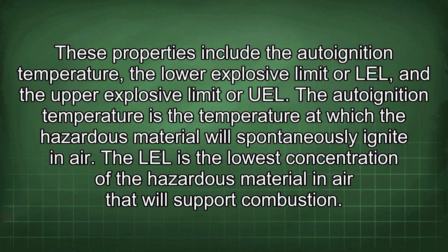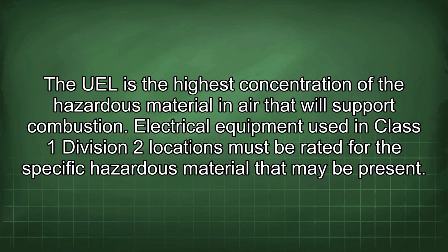The auto-ignition temperature is the temperature at which the hazardous material will spontaneously ignite in air. The LEL is the lowest concentration of the hazardous material in air that will support combustion. The UEL is the highest concentration of the hazardous material in air that will support combustion.